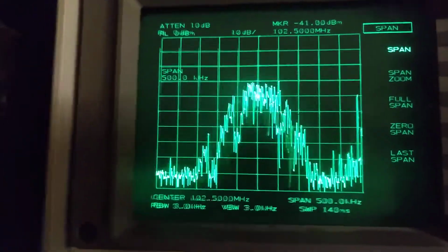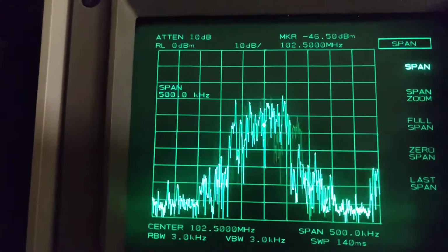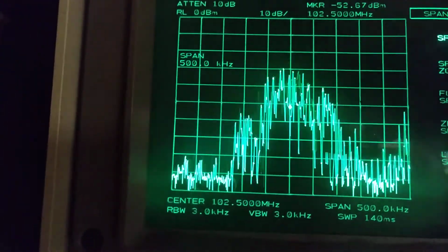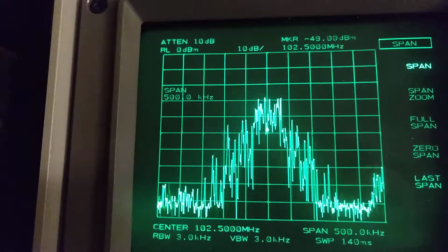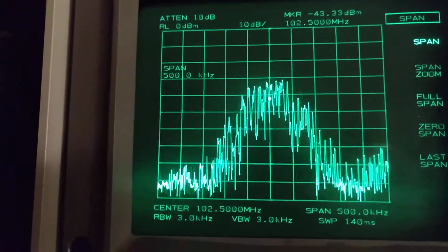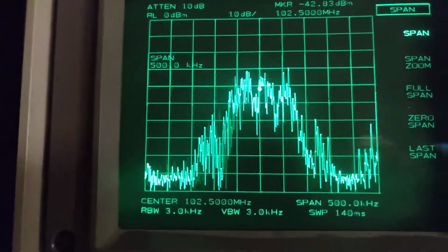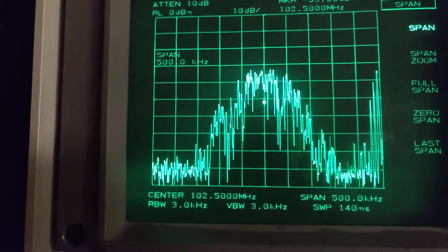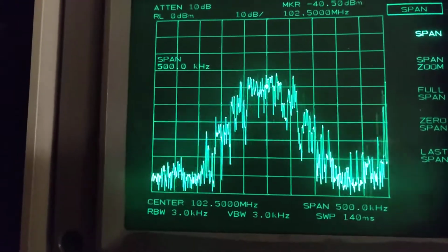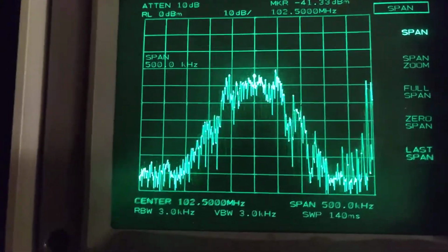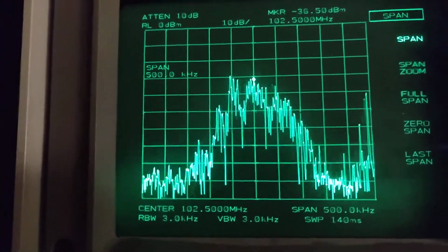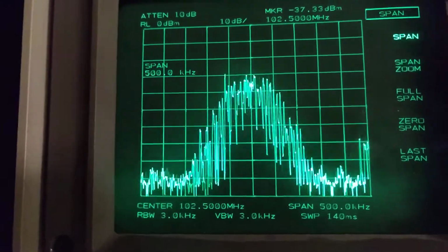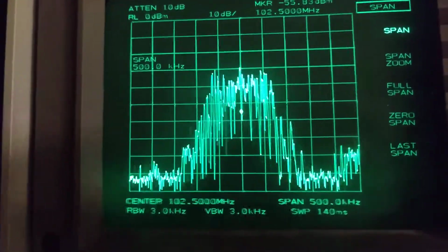If I do this with a spectrum analyzer, now you can see that the amplitude of the marker is of course erratic, because I am seeing the spectrum density of the signal, and while it is frequency modulated, it spreads its power into frequency, while the total power is always steady and constant, because it's frequency modulated, not, for instance, amplitude modulated.